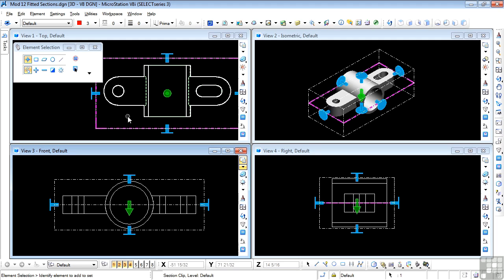And I'd like you to experiment a little more with the handles and the location of the section and the direction of the section. And then after that, I'd like you to, on your own, make a vertical section. And this time, the vertical section should go in this direction across the bushing. And of course, for that vertical section, you would not make that in the top view. You'd make it in the front view. So we have again a front section to work with.